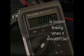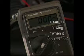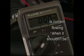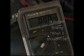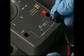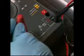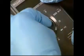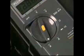Is current flowing when it shouldn't be? A circuit that is using current when it shouldn't be will cause a drain on the battery when all systems are off. To use an ammeter, insert the black probe into the port labeled COM for common. Set the red probe into the meter port labeled amps. Set the rotary dial to the ammeter function for direct current.